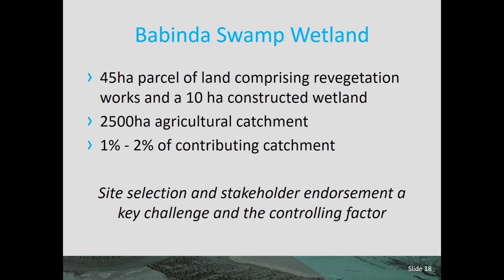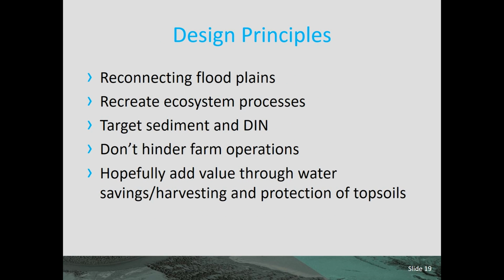Again, the design principles for this particular project were reconnecting the floodplain, recreating ecosystem processes, removing sediment and dissolved organic nitrogen. Obviously we couldn't hinder any farm operations or reflood neighbouring farms.